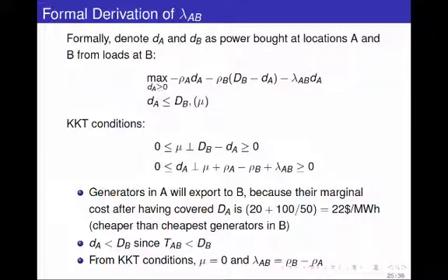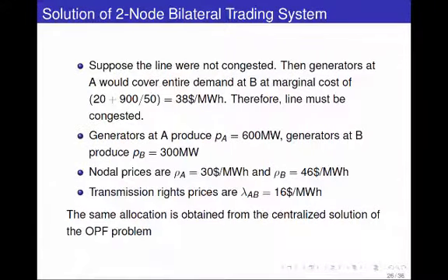So also here, this will be a strict inequality and the nu will be 0. That means that basically the mu goes away here. This is an equality. So this argument I made earlier on intuitive terms, you can derive it from the KKT conditions of the competitive market. The price of the transmission rights is exactly equal to the price at the expensive area minus the price at the cheap area. You can derive that formula. So using these tools is something I would really like you to learn how to do in a systematic way in the course.